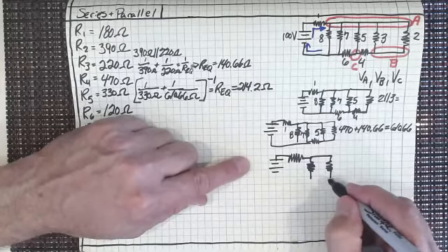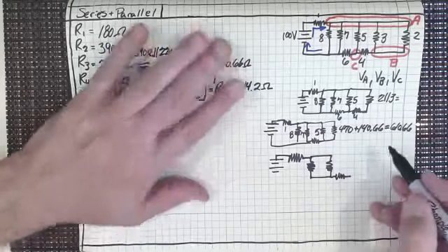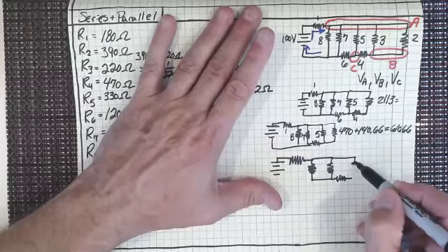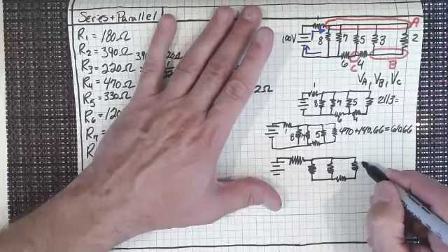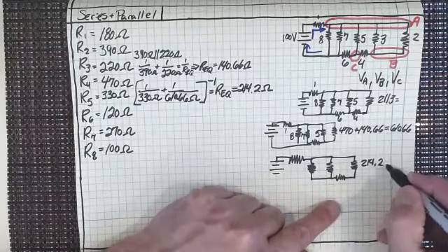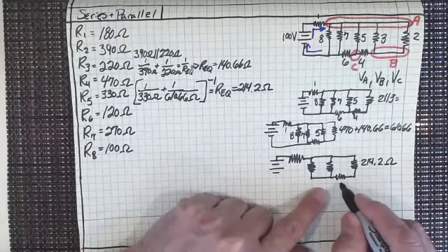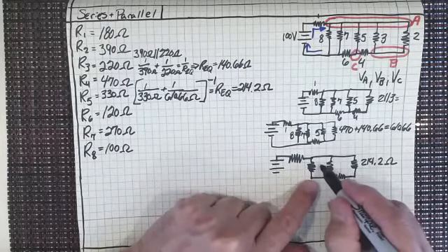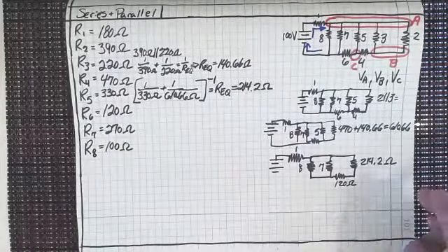We still have the resistor here, number 6, but instead now we have number 6 in series with this resistor that was the equivalent resistance, 214.2 ohms. So this one down here, which is 6, is 120 ohms. So we'd add those two up, and of course this is still number 7, this is still number 8, and this is still number 1.